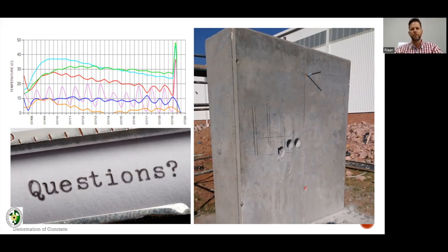Ultimately, the client pays for that reinforcement that goes in, and for the labor that installs the reinforcement. So my 2 cents is this: if you can have a two-pronged approach, you try and plan around how the actual constituents will react, you try and mitigate with preventative measures, and you can also design for those values. You've done the homework now. You know what the temperatures are. You've done the trial panel. Now you can go and revisit the design and refine it perhaps, and maybe save a client a bunch of money if that is the case.